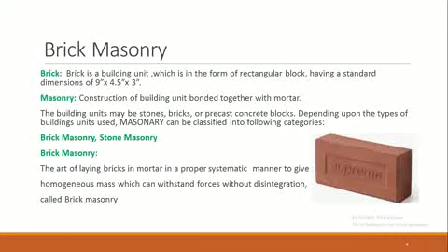So brick masonry is basically the art of laying bricks and mortar in a proper systematic manner to give a homogeneous mass which can withstand forces without disintegration. And a picture of the brick has been shown with a visible frog at the center of the brick, with a trademark as Supreme.